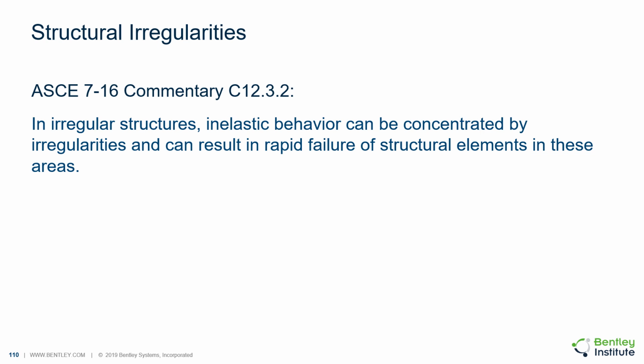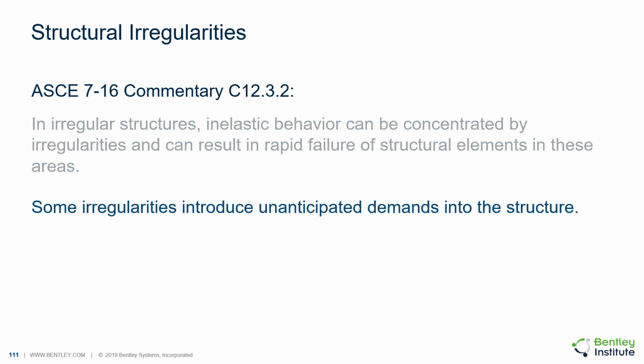However, just as discontinuities or notches can cause stress concentrations on a small scale on a plate or a part, structural discontinuities and changes in stiffness in a structure can cause inelastic demands to be focused on members in those areas. This may cause these members to fail well before the rest of the seismic force resisting system is fully engaged. Some irregularities introduce unanticipated demands into the structure.